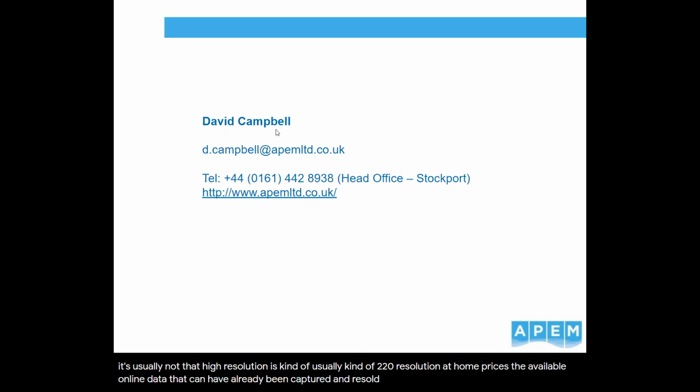What I've been talking about here is bespoke surveys for this type of work. There's quite specific conditions that you need for habitat mapping. Certainly when you're looking in channel, not necessarily out of channel, you've probably got a bit more latitude, but certainly in channel work, you need to be going when the river's fairly low, where you've got good overhead conditions in terms of sunlight, and let's have considerations for certain times of year, in terms of how much vegetation's in the river, for example.